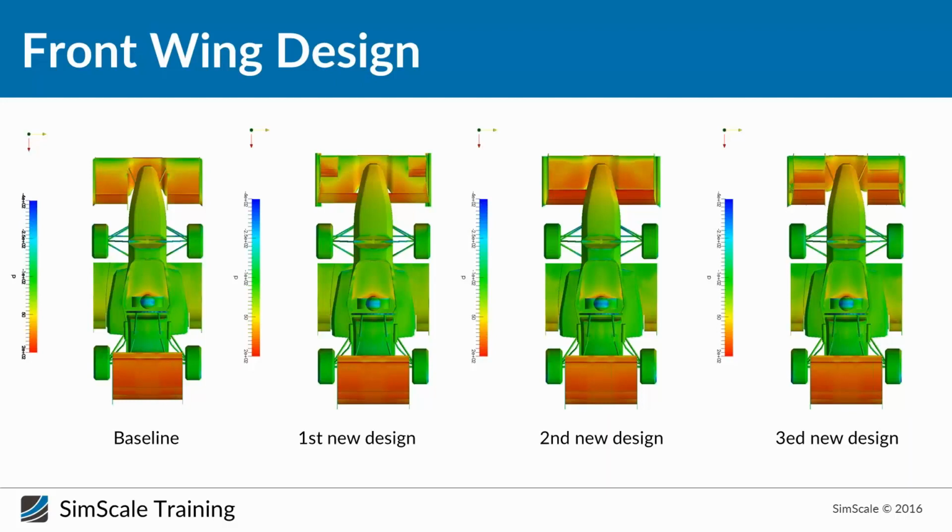But if you take a look at this wing, like I told you, the second wing, we have created the cascade elements, and I know this from my previous experience, but here it is really clear that the cascade elements are used to control the flow over the tires and will not really help you to create more downforce, because first of all, the elements are really small.